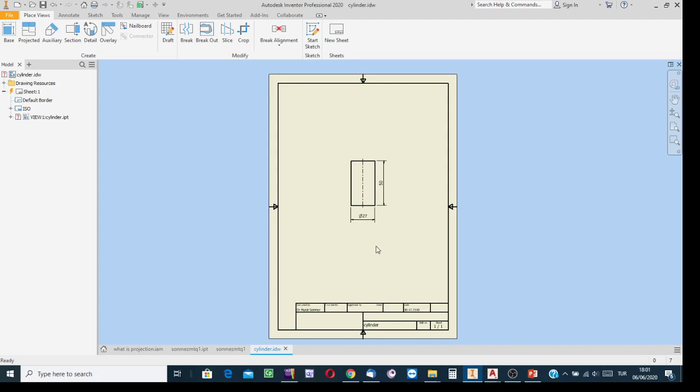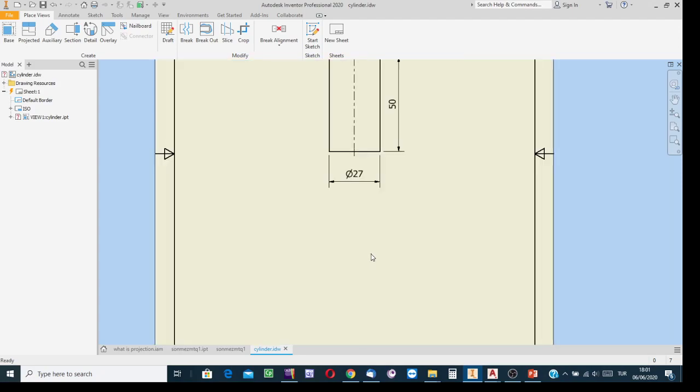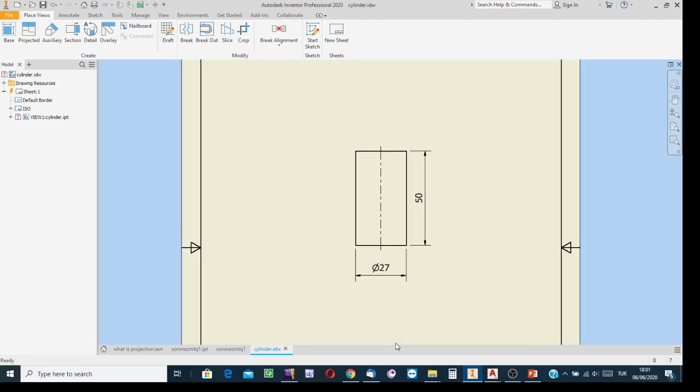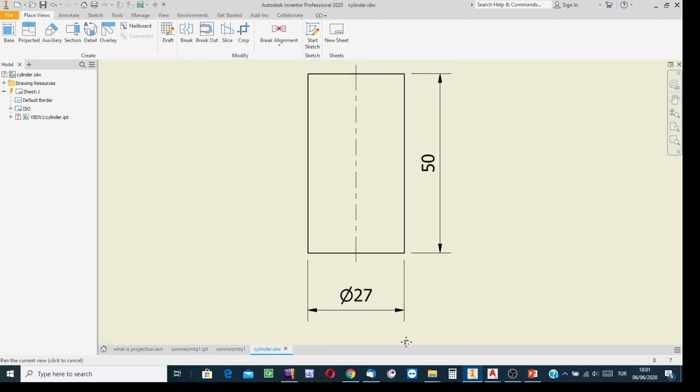How? Here at that stage, the learning outcome on dimension format will help you. In accordance with ISO standards, dimensions are shown above the dimensioning lines and always in alignment. You learned this. So you see these dimensions, these numbers, have been shown above the line and in alignment, parallel to the dimensioning line. This means it is in accordance with ISO.